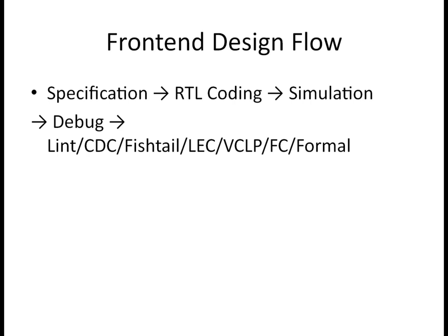CDC is clock domain crossing, where a signal travels from one domain to another. For that reason, we need to make sure all the data reaches the destination correctly, so we'll be using clock domain crossing checks. And next is Fishtail, which is also a tool from Synopsys, the Synopsys Timing Constraint Manager, where we make sure our RTL is aligned with the timing constraints given by the designer. So we'll make sure the RTL is in sync with the constraints. Here we will be doing the constraint lint checking.